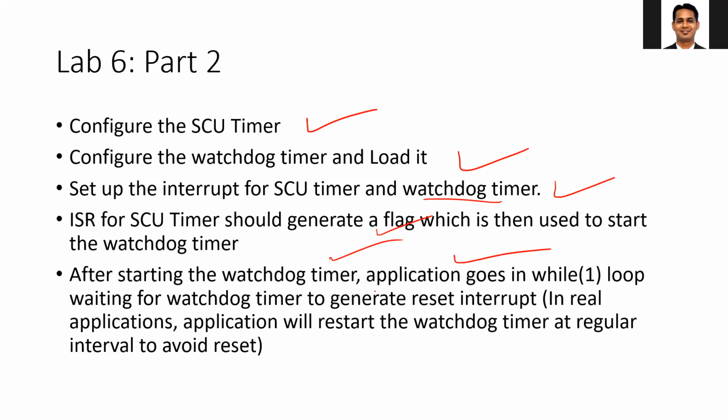Your processor will get reset. Then your board will get switched off. Then you need to configure the board again by downloading the ELF and bitstream file, and then sample the corresponding reset status register to know the status of your watchdog. Okay, so with this we have completed the discussion on the watchdog timer. Now we'll go to our lab session and see how we can verify the functionality of the watchdog timer.